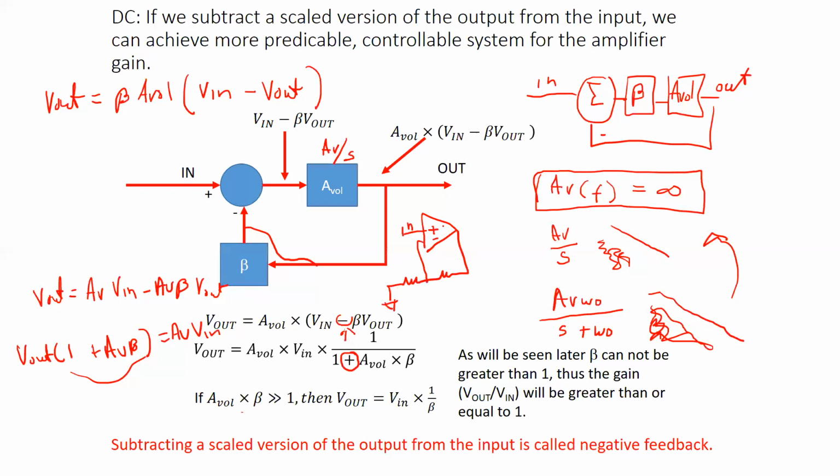So this is an op-amp model. Inside the op-amp is a summer and a gain stage. I could draw an op-amp model around this. This would be my plus, and this would be my minus of it, because it does the summing. Well, notice I have R2 and R1.